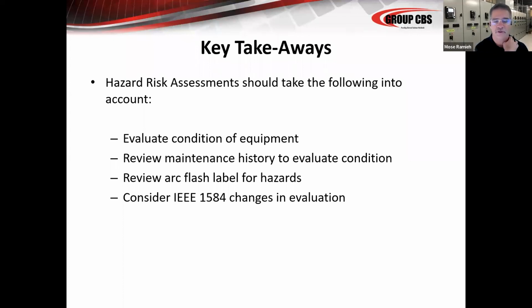You definitely want to review your labels. You get to routinely walk plants, and sometimes they make no sense, right? The arc flash level is higher in one location and lower in another when I would expect them to be the same. Those types of things, just to review those. And then once again, every 5 years, reviewing your system. And then anytime you make any changes, right? If you add a system line, we want to make sure that you get a study done.